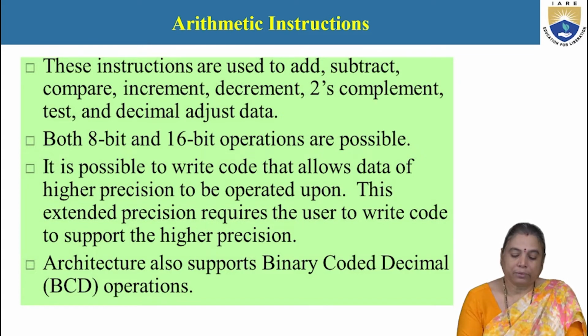Both 8-bit and 16-bit operations are possible in the case of arithmetic instructions. It is possible to write code that allows data of higher precision to be operated upon. This extended precision requires the user to write code to support the higher precision. Architectures also support BCD, binary coded decimal operations. The data can be represented in binary coded decimal form.